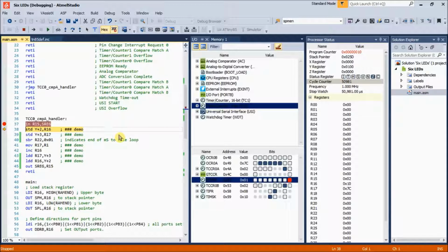In other words, you're going to load a value in there, you're going to use it for a moment, and it will quickly become irrelevant what's in there, because if anything else is going to use those registers, they won't depend on a value that's in there, they'll be setting a value in. So typically, if you want to load a register lower than register 16, then you would load the value into register 16 and then transfer it to register 4, for example.